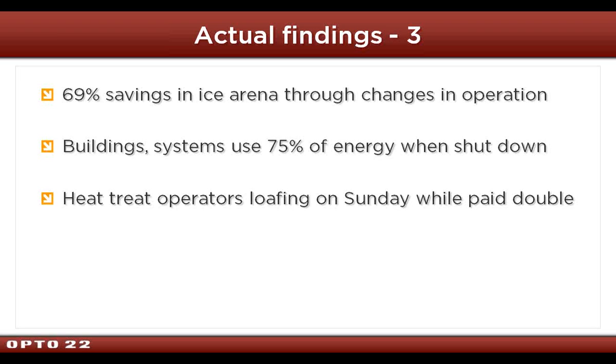We monitored some plastic injection molding presses up at the RCA plant in Indianapolis, and we found that the presses that were off, out of service, not even an operator using them, were using, I think, 85% of the energy that the ones in full operation were. They had hydraulic and cooling systems that ran full out, whether they're in use or not.